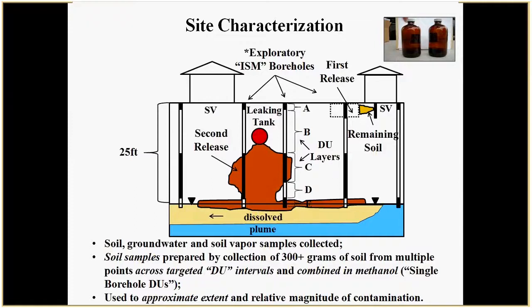and it's in a lot more detail in Hawaii's guidance. And unfortunately, in the ITRC TPH Risk document, the people who were writing the section on site investigation weren't familiar with these incremental sampling methodologies, their techniques. And there may be some notes in there about collecting discrete samples in the subsurface. But from our experience, these aren't going to be reliable. We would definitely recommend using ISM type samples.